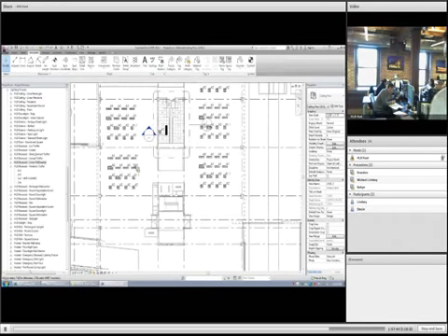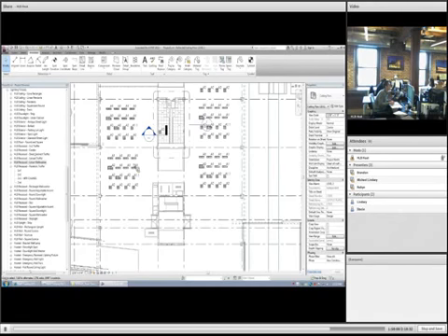There are 2 different types of lines in Revit. There are detail lines and model lines. Model lines are 3-dimensional, and they show up in every view. Detail lines are view specific, and they only show up in one view. One other thing is, once you get into the families, you'll see symbolic lines. Symbolic lines show up only in plan, or elevation, or the view that they were created in. Let's say for now, symbolic lines are like annotation detail lines.